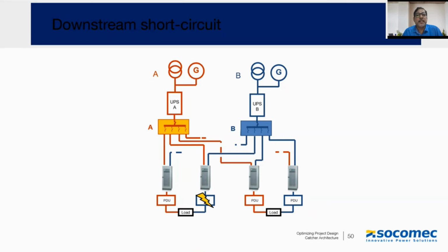In case of a downstream fault, say between the load and the STS, the distribution system, in a normal condition this would be directly seen by the upstream source and initiate the tripping of the source or transfer to other source, and maybe propagate the fault to the other source B as well. A possibility that can exist.